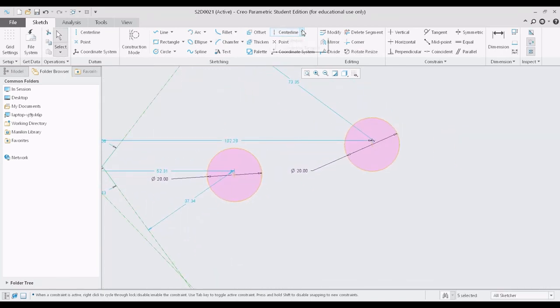So a center line with a tangent is something different. We can create a center line which is tangent to the entities. This is especially used for curved surfaces where there is a possibility of creating a tangent line. Okay, so let me just click on center line and tangent, and Creo is giving us a suggestion over here to select the start location on arc, circle or ellipse, right?